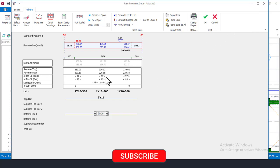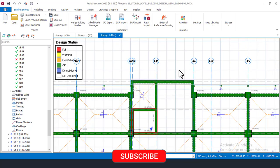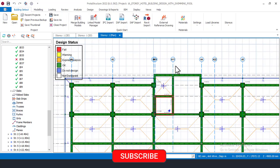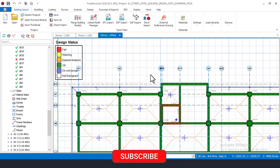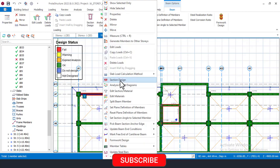So with this right now, I have checked this beam, and this beam looks okay. So right now, come here and then click on okay here. With this now, I have checked this particular beam here, and I am okay with it. So always check your beams, alright, to see the kind of reinforcement that the software is giving you. So I'll come again right now and check on this. I'll check it sequentially, and right click here and then click on design here.